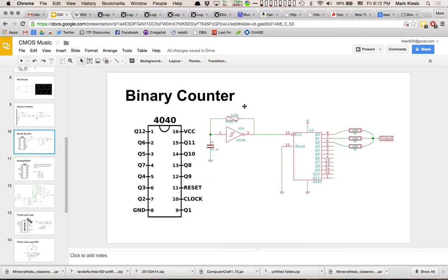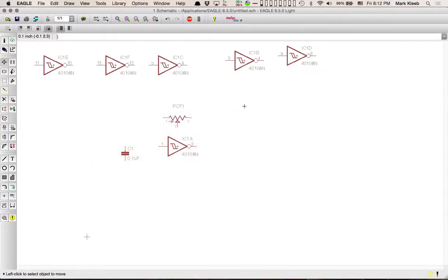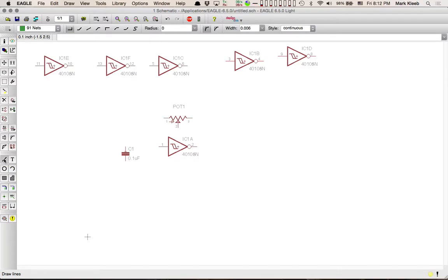The rheostat, right? When you connect the middle pin of a potentiometer to one of the outer pins, so you've only got a variable resistor, they call it a rheostat. So what I can do here is just connect pin 2 to pin 1. So down here, next to the T, this is the text tool, this is the wire tool. Wire tool, like everything in Eagle, is a little counterintuitive. I'm going to click on the place that I want to start my wire. So I'm going to start on the middle pin here at 2.